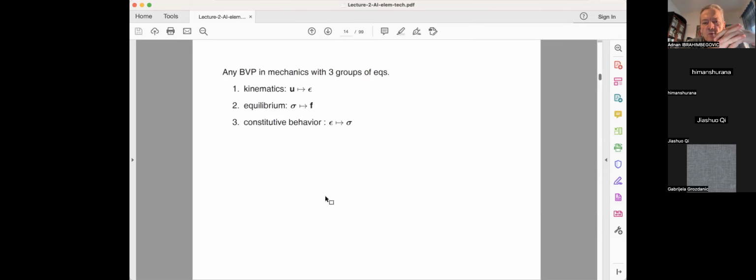So we will need, if you want, 21 equations. Basically, first we'll have a kinematics equation to get the strain from the given displacement field, defining the strain as the symmetric part of the displacement gradient. Then we'll have the equilibrium equations, which has 3 linear momentum equilibrium equations, and then 3 angular momentum equilibrium equations. And then we'll have a constitutive equation, which relates all the components of stress with the components of strain, to follow the count with as many equations as number of components.